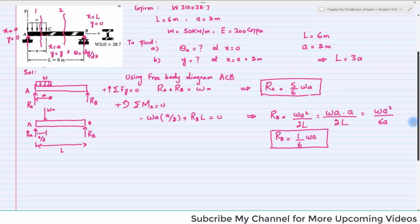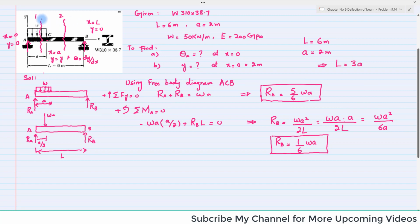So let me move and take the section at this one, which is at a distance of x. Clear? So I will first draw it over here. This is the beam and some portion of the beam. This is reaction force RA. Clear? There is a uniformly distributed load W, and it is acting at a distance of x.